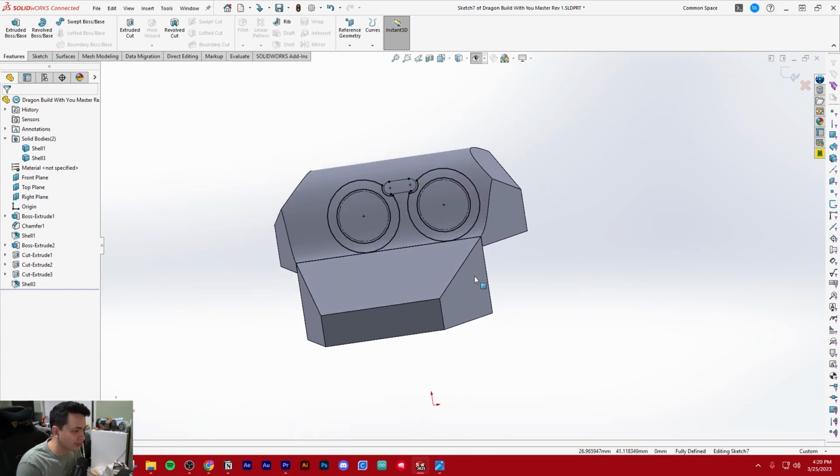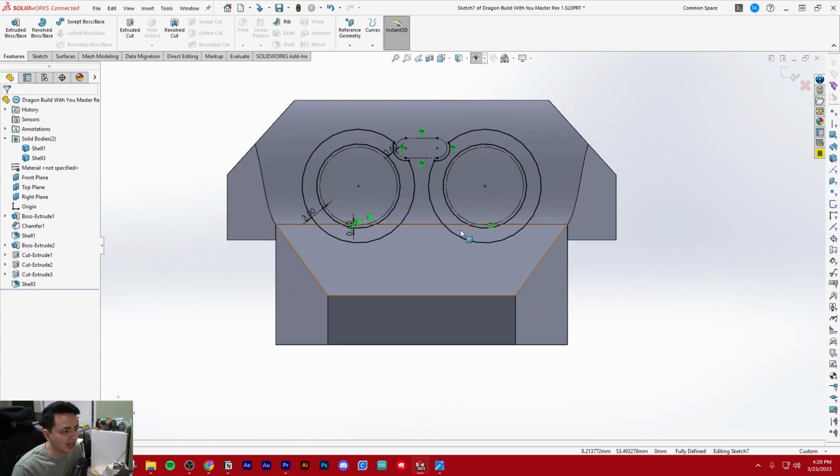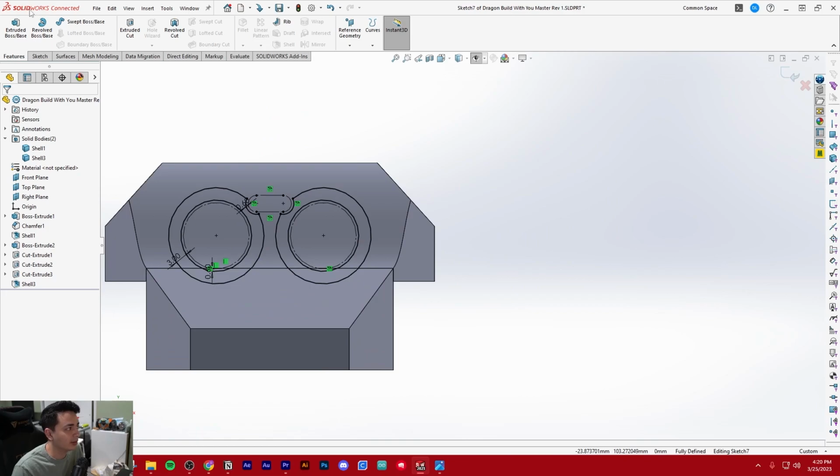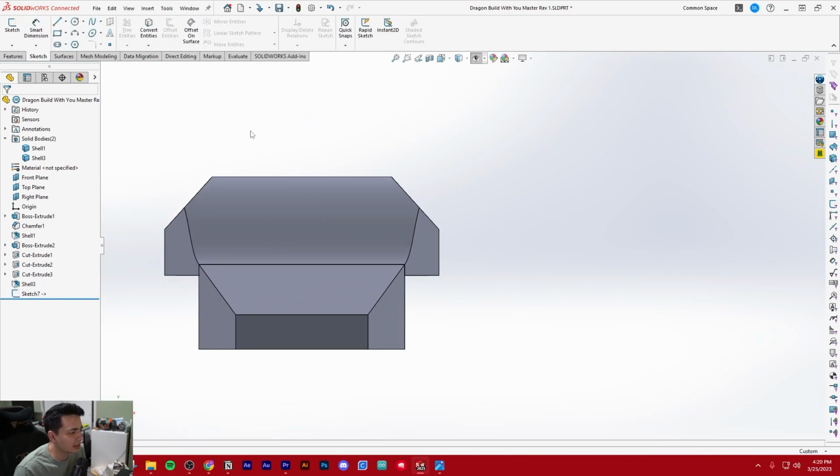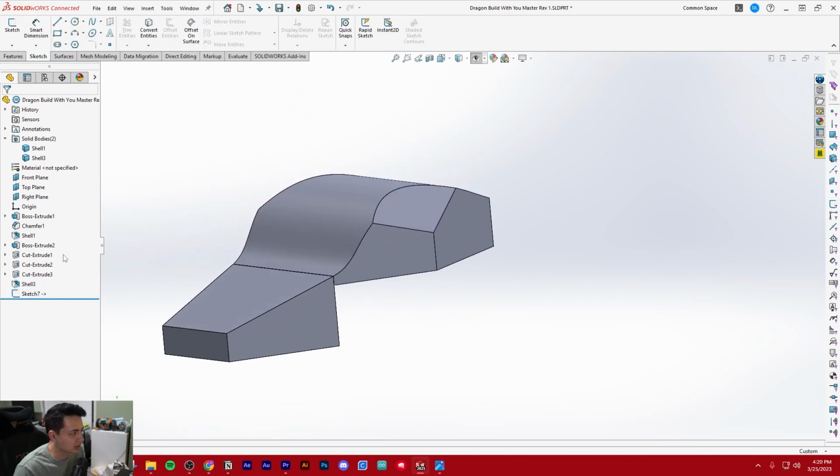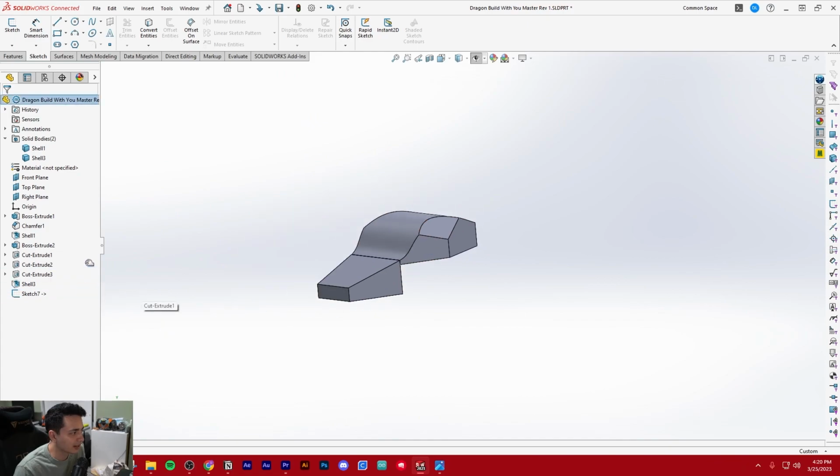And we're trying to tell this sketch to extrude all the way up to this surface. But if we look at it from the front view, this piece of plastic that we're trying to build is dipping below our part. So ideally this bottommost part of the circle should be above the line. So how do we fix that? We need to add a little bit of extra space. So let's go back. Let's roll back and see how we built this.